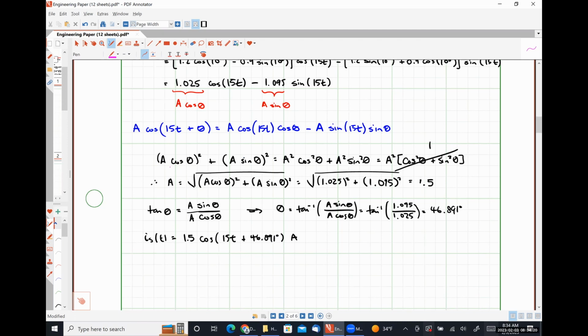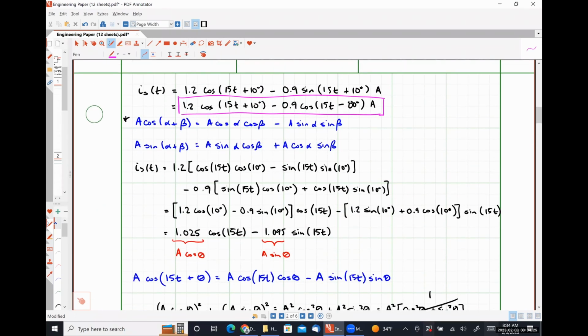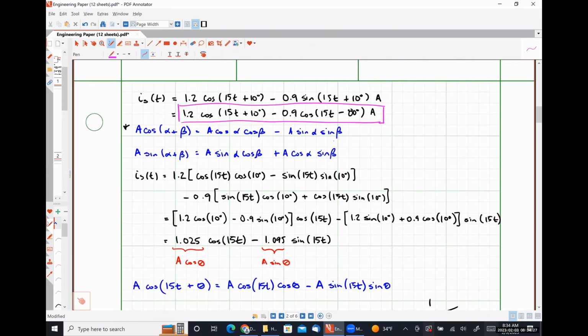That is not a coincidence, okay? So complex numbers carry the same information as a sinusoid. They have a magnitude, a frequency, and a phase angle. We are going to use the cosine representation for all of our sinusoids because that is the real part of an exponential complex number.